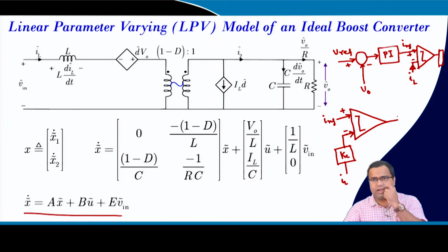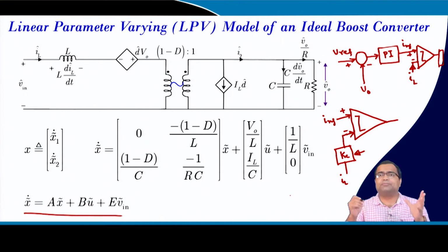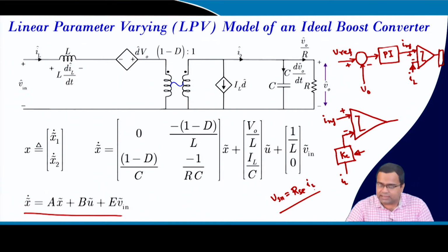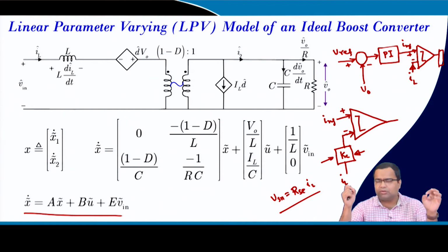And again it goes to the latch. So, this current loop gain can already be placed because we said the sense voltage of the inductor current is RS equivalent into IL, right. So, it is coming from the sense resistance. Sometimes we need to intentionally change the gain to do some optimization, and that is very much possible in digital control, as well as in analog, although it is difficult, but it is possible.